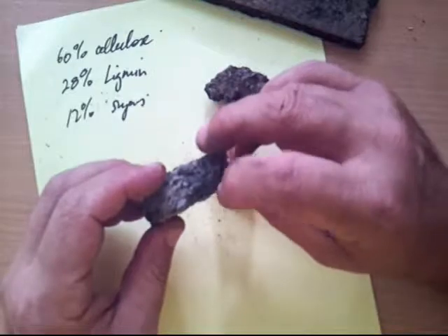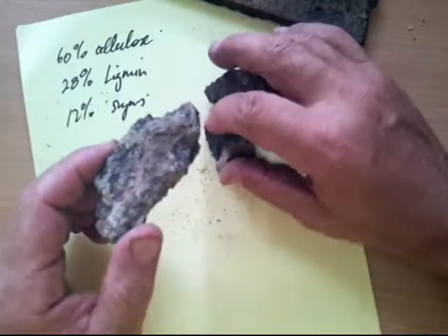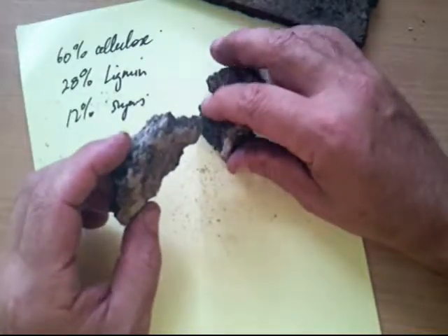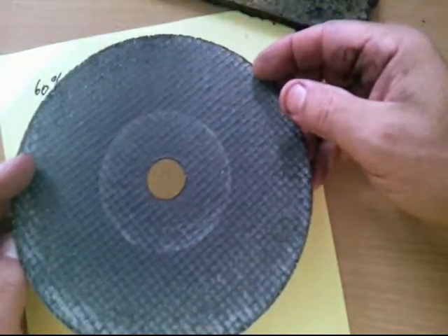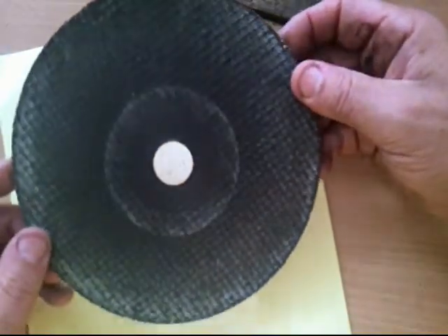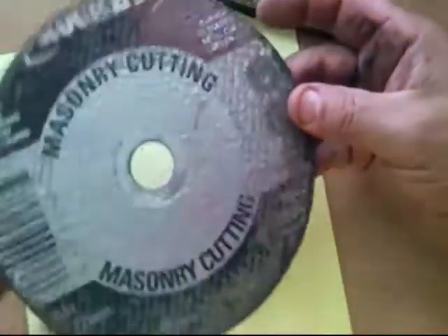It can be heated up and rejoined, which is another great advantage to it. And it can be made up in large or small quantities. So it can be applied at fairly low temperatures. It flows at quite low temperatures, so it's not necessary to heat it up much. It's quite convenient as a road system. And of course that's why you see so much of it. Alright, so that's asphalt.